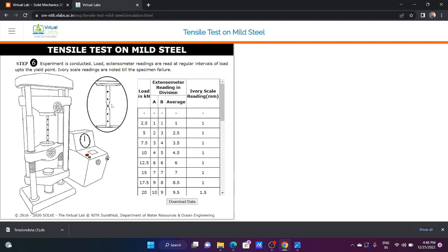And here the material fractures. The ductile material will be cut in a cup and cone shape, which will be clearly visible. Now you have to stop the machine by pressing the red button. Go for the next.